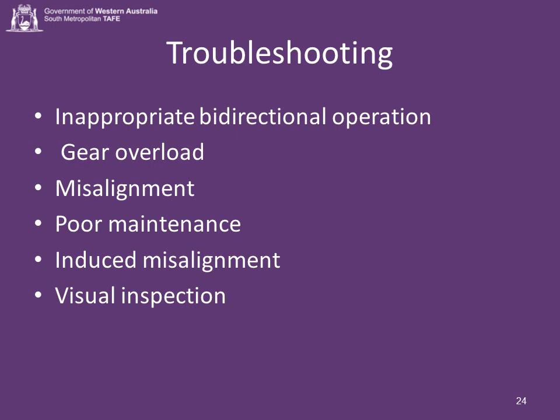Misalignment, both real and induced, is also a primary root cause of gear failure. The only way to assure that gears are properly aligned is to hard blue the gears immediately following installation. After the gears have run for a short time, their wear pattern should be visually inspected. If the pattern does not conform to vendor specification, alignment should be adjusted.